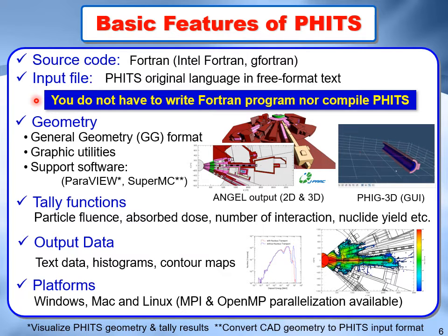Of course, if you are familiar with Fortran, you can use PHITS more deeply by combining it with your own source generation or tally definition programs written in Fortran. The geometry in PHITS is described in general geometry format, so-called GG, and it can be visualized by built-in program named Angel and GUI software named Fig3D.